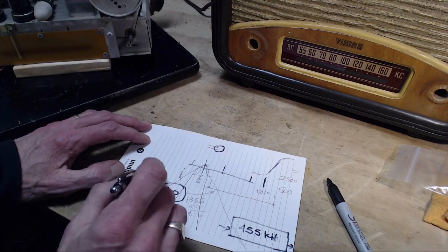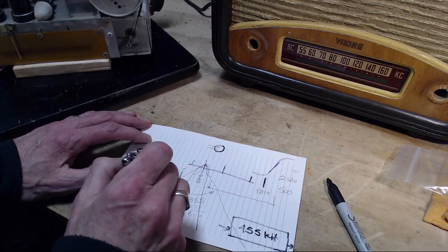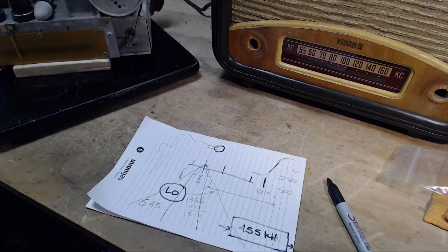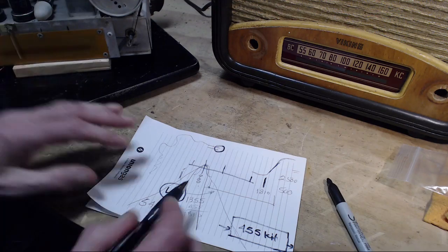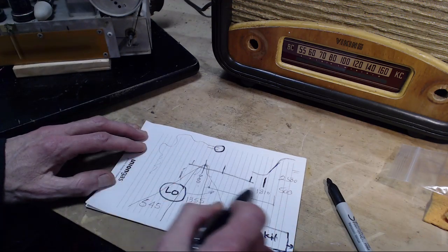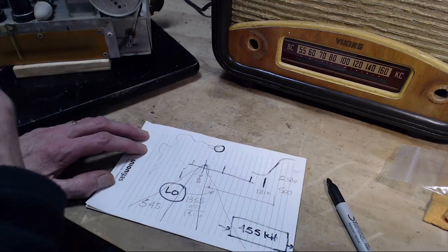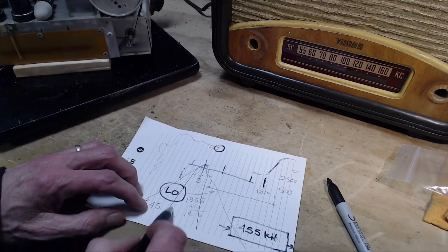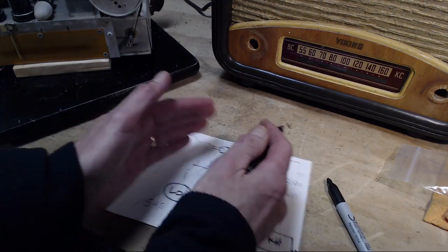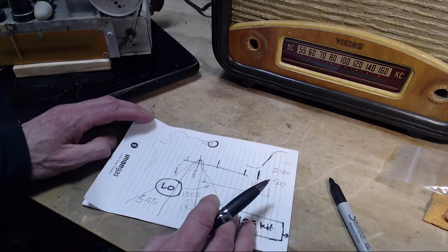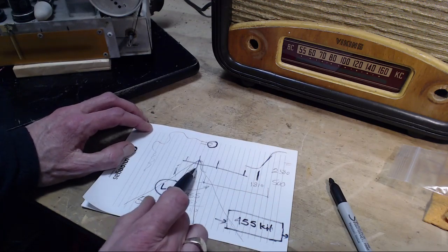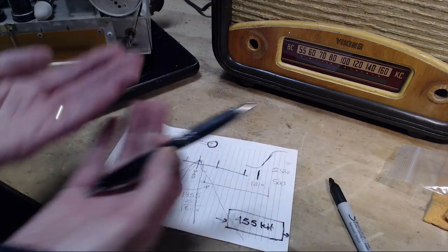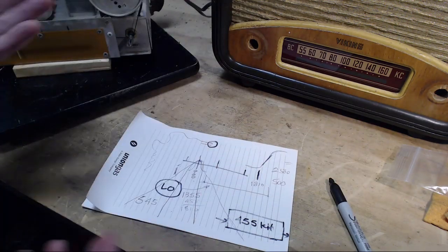And there's a chance in some radios, the cheapest, worst radios, that the antenna would just be a wire going right to one of these grids with no tuning. It means everything that's on that piece of wire, which would extend right up shortwave, everything you can think of, is stuck right on the grid there. There's none of this happening, none of this quieting out the other stuff. It's all there. And worse yet, if it all gets into here, it's all doing that mixing, dividing, adding thing.